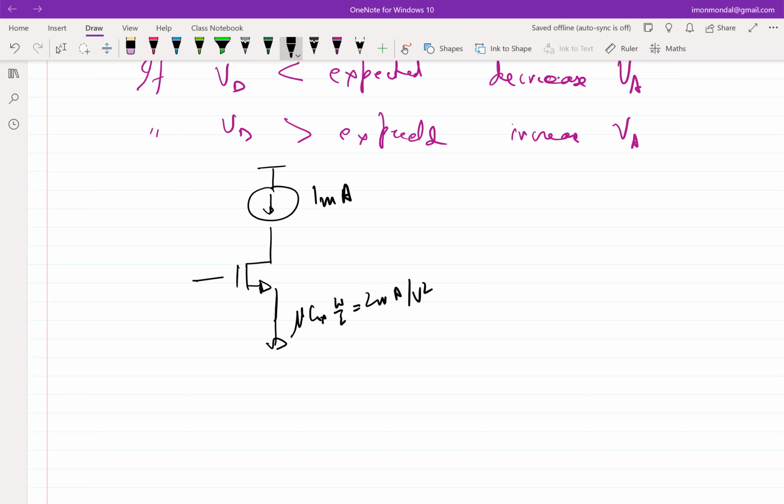We will. So coming to his question, let's assume this is what it is, and you applied a voltage, let's say the threshold voltage is 1 volt and I applied 3 volt. What do you think will happen here? Will this be in the linear region or in the saturation region? It is easy to see if I sketch the ID-VDS plot.